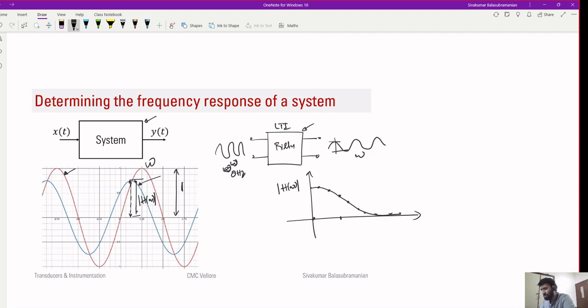How do you find the phase response from these input output graphs? Here, phase response is easy. This is your original sinusoid, the red line, but the blue sinusoid, the output from the system, not only has a different amplitude, but it's also shifted in time.